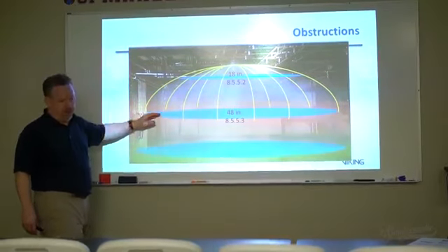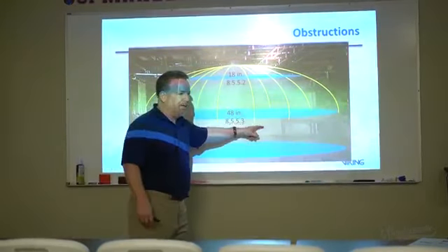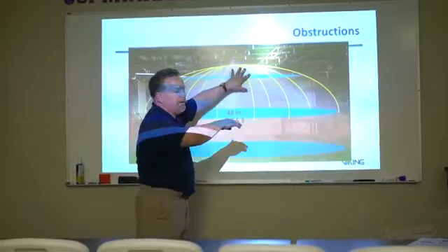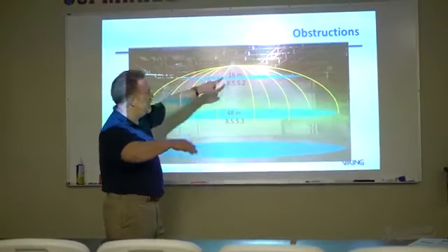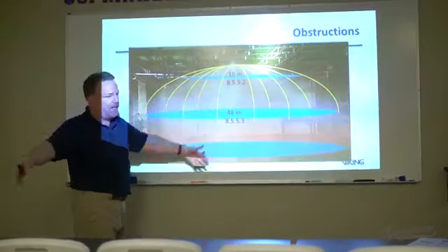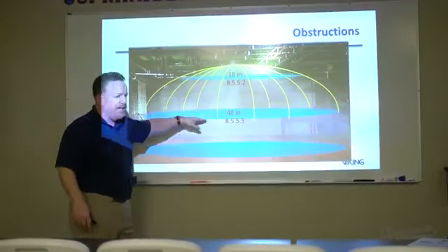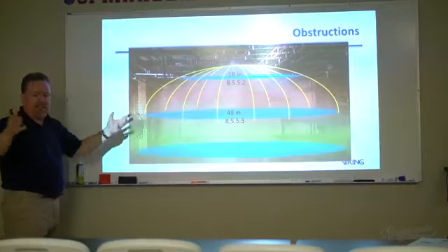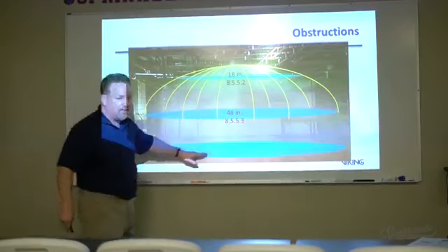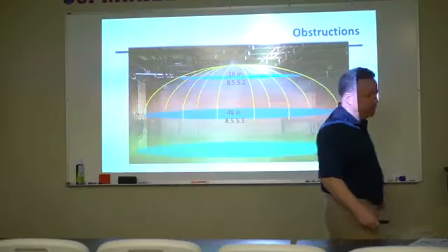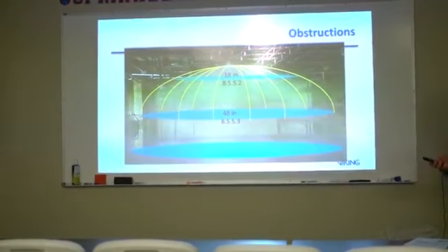Slightly different rules come into play for each of these sprinklers. In other words, the spray pattern is fully developed within the 18-inch plane. It's fully developed, it's going. Now we've got this 48-inch plane. Anything in here could prohibit it from getting to the floor, and that's a different set of rules that we're going to engage with.